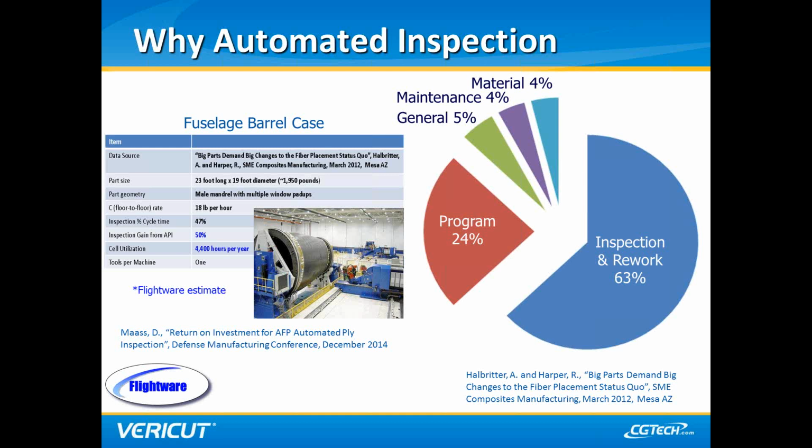So when we take a look at these machines, and we talked about the investment going into them, you'd like to see that you're laying up the part nearly 100% of the time. Realistically, it's not going to be 100% of the time, but you'd like to see 70, 80% of the time you're actually manufacturing, that you're laying material on your part.